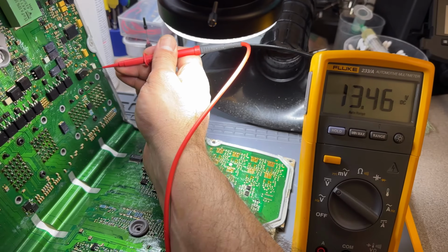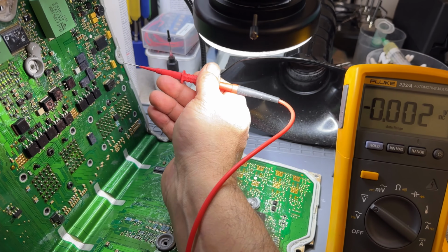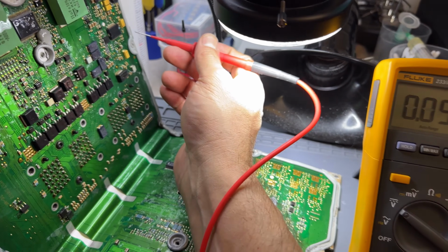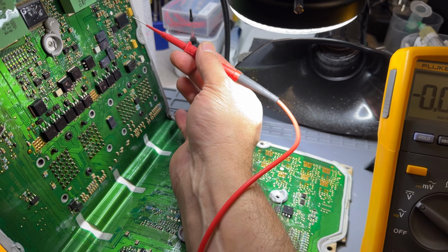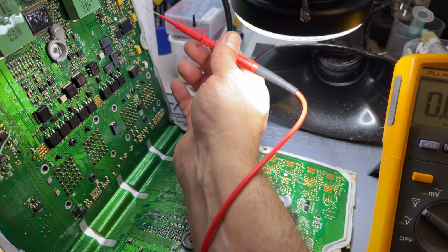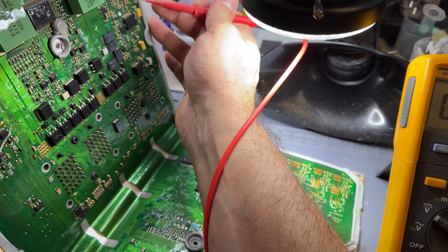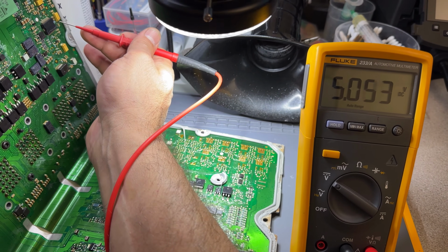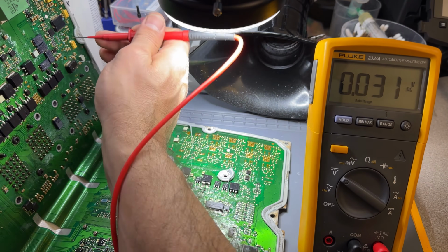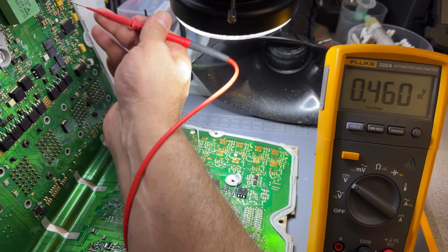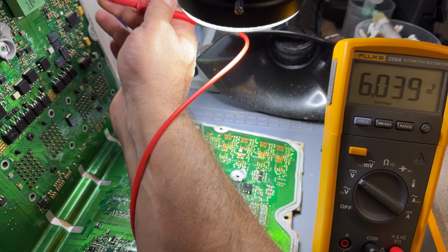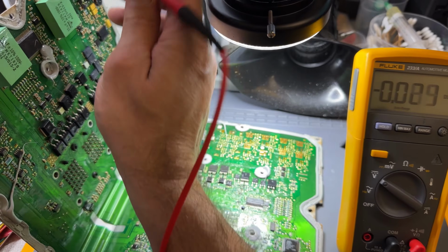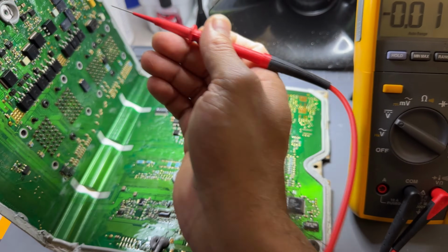And we got battery voltage. This one will be at 3.3 volts, 3.4, so it's fine. This will be 5 volts in here, and you got the 5 volts. These two should be 6 volts each. Sorry, guys, let me make sure that you see that. 5 volts, and right here, 3.4. And then we got 6 volts here, 6 volts in the other one. I'm trying to do this carefully because, again, it's hot.